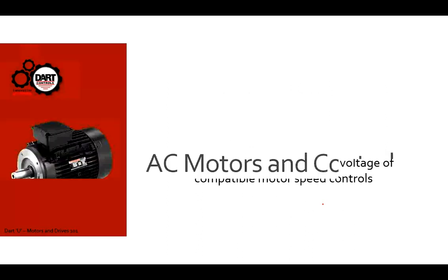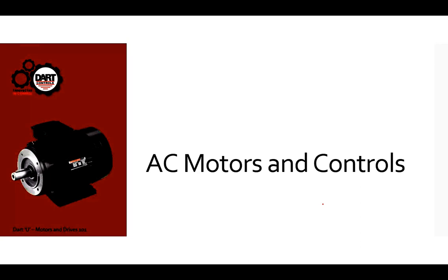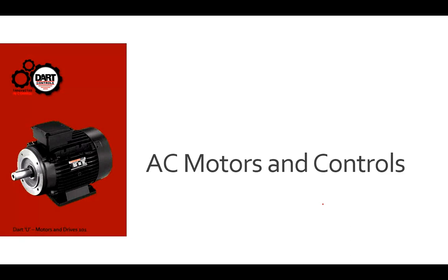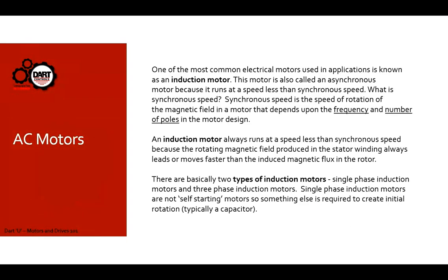Okay, let's switch over to AC motors and controls. So, one of the most common electrical motors is called an induction motor. It's also called asynchronous because an induction motor always runs at a speed less than what's called synchronous speed. We'll try to define this as we go.